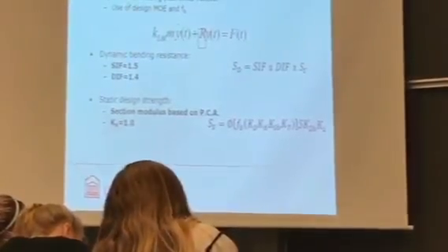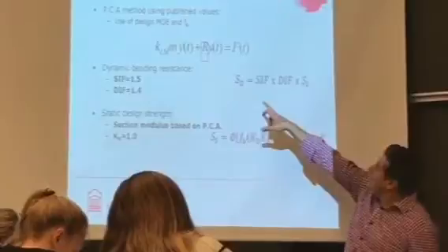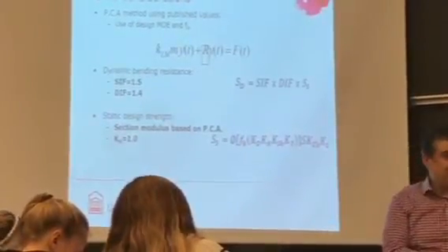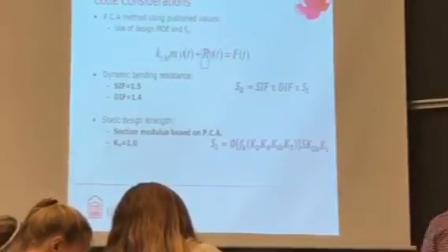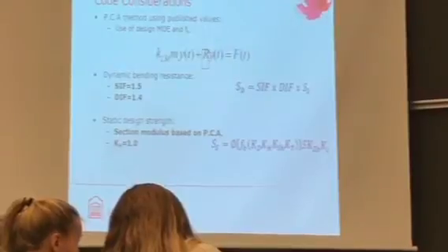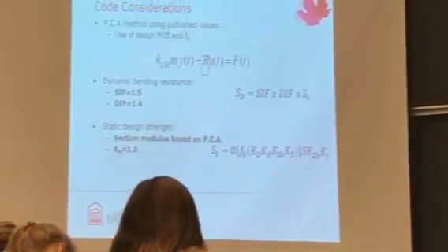You plug it in there. You do your dynamic analysis. You get the deflection. You go back to the code and you say, does this deflection mean it's broken or not broken? And now you know how to do blast design.